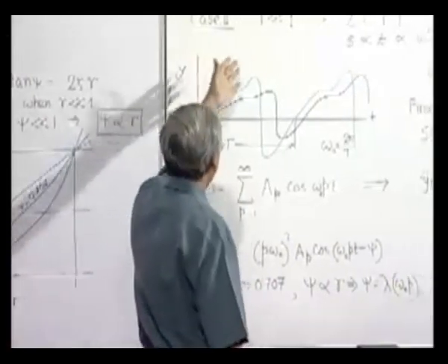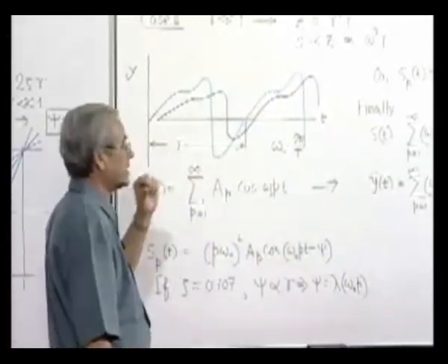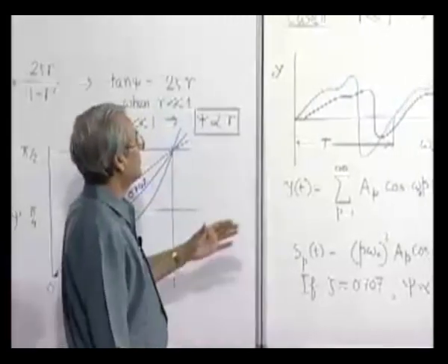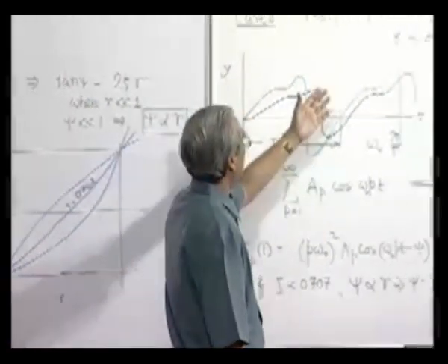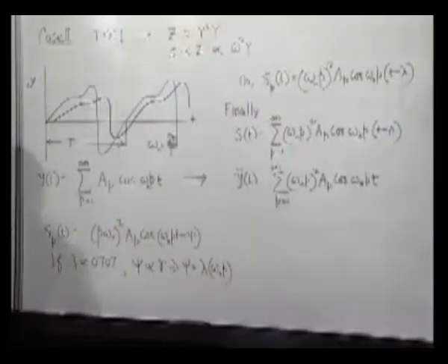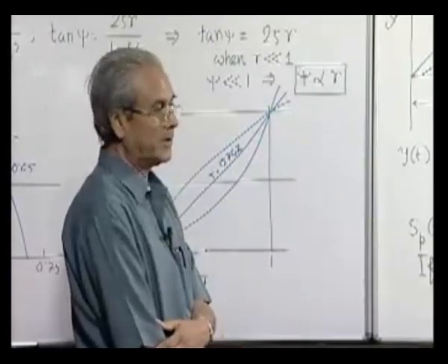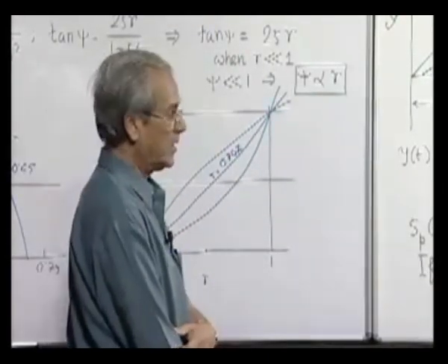In the other case, when the natural frequency of the system is very high and the operational frequency is generally very low compared to that, then what we generate as a voltage using a piezoelectric pickup is proportional to the acceleration of the system, and they are called accelerometers.